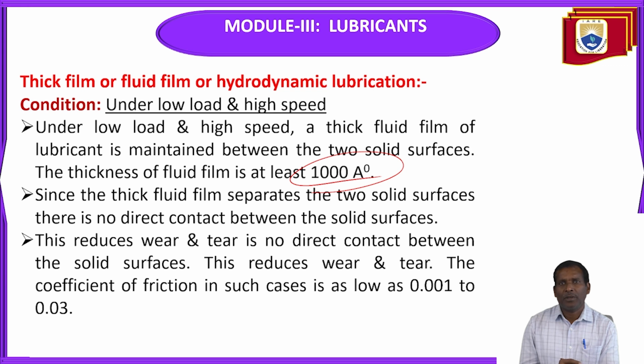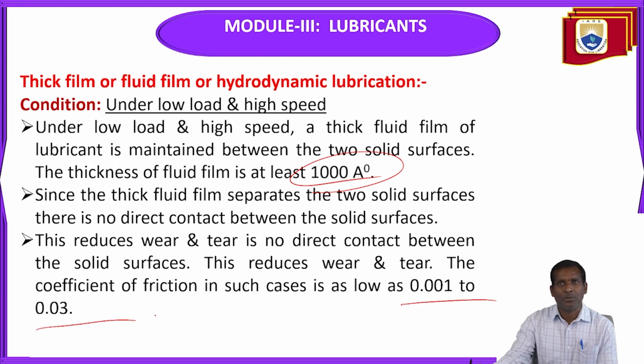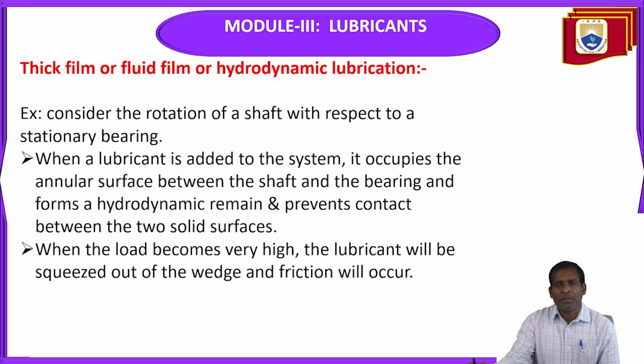So this reduces the wear and tear. There is no direct contact between the solid surfaces. The coefficient of friction in such cases is as low as 0.0001 to 0.03. So this is thick film or fluid film lubrication.